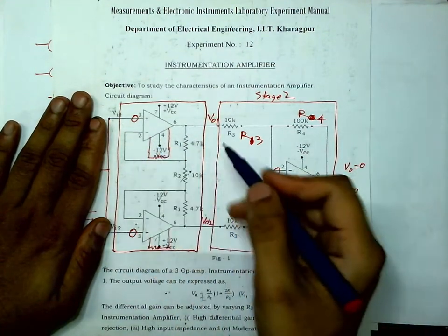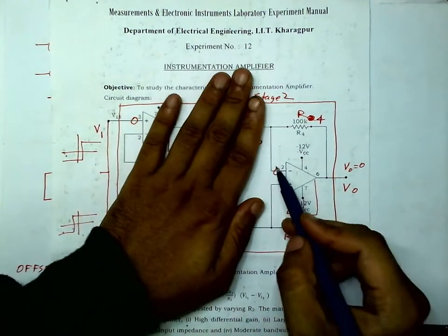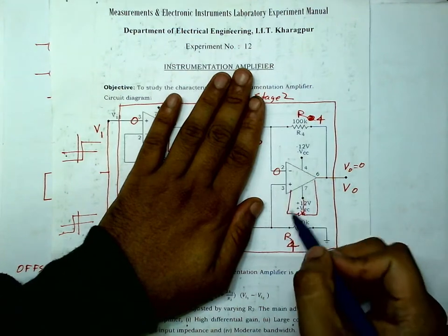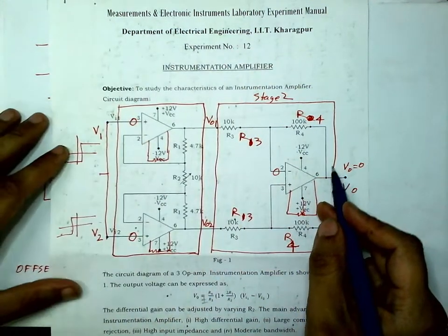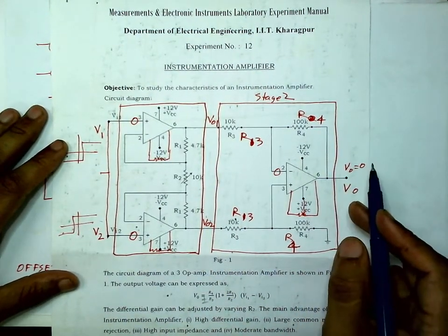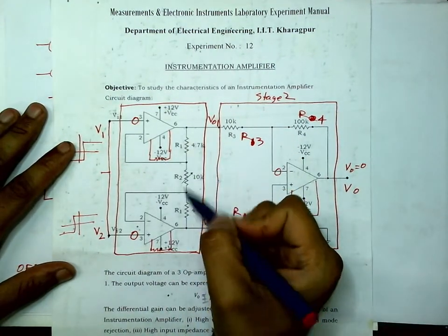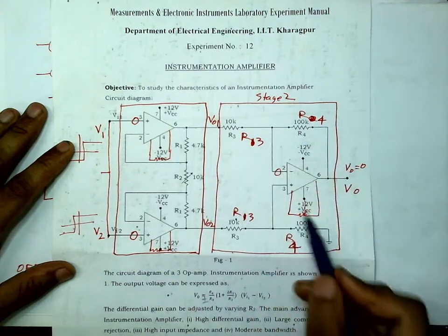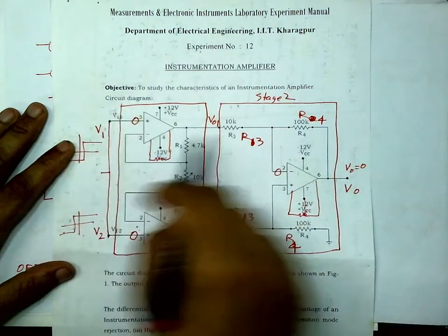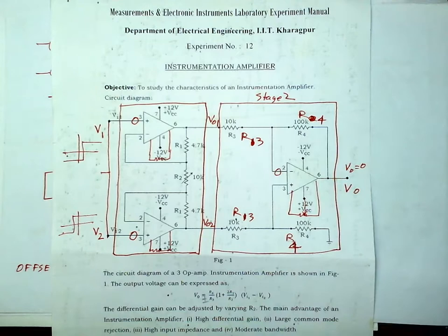Then after that, maybe you do it individually, short circuit this one, adjust this to make that 0. But actually maybe you can also take care of the non-equality of these resistances by adjusting these offset voltages, etc. So this becomes a bit more involved.